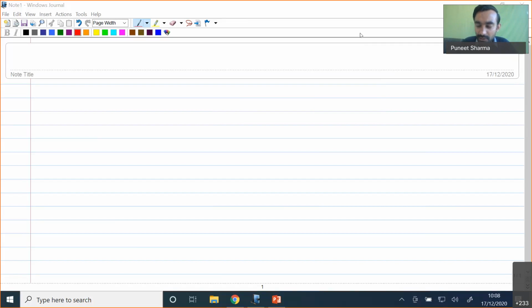Then we obtained the mathematical form for Cp and Cv, and later on we found that Cp and Cv take the form of thermodynamic properties. So that's why we also referred to Cp and Cv as thermodynamic properties of the system. Later on, I tried to show the magnitude of specific heat, particularly for solids and liquids, and we came up with the idea that for solids and liquids Cp will be approximately equal to Cv, and we define a single specific heat.